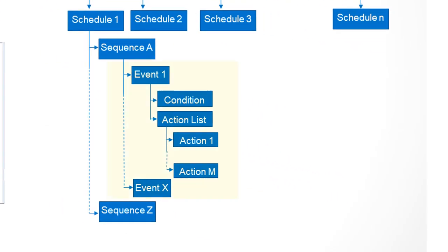An event must have a condition, which determines when the event will be triggered. The event condition is a logical true or false evaluation, and the actions are manipulations in the simulation case. When the case meets the condition of a current event, actions are executed. At least one action must be fully defined for each event. Usually, only one event is evaluated and allowed to execute at each time step.